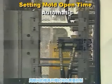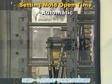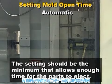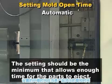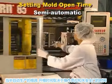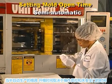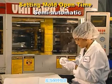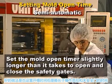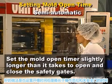The time between cycles, that is, the mold open time, must also be controlled. When operating in the automatic mode without an operator, the setting for the mold open time should be the minimum that allows enough time for the parts to eject. When operating in the semi-automatic mode, the mold open time is controlled by the opening and closing of the safety gate by the operator. It should be kept consistent. To maintain consistency, it is a good idea to still use the mold open timer and set it for slightly longer than it takes the operator to open and close the safety gate.